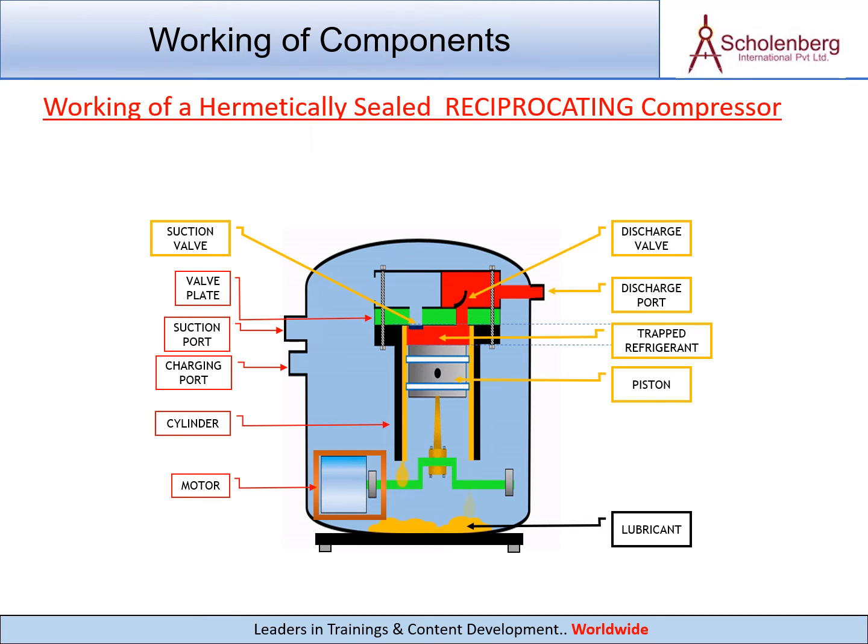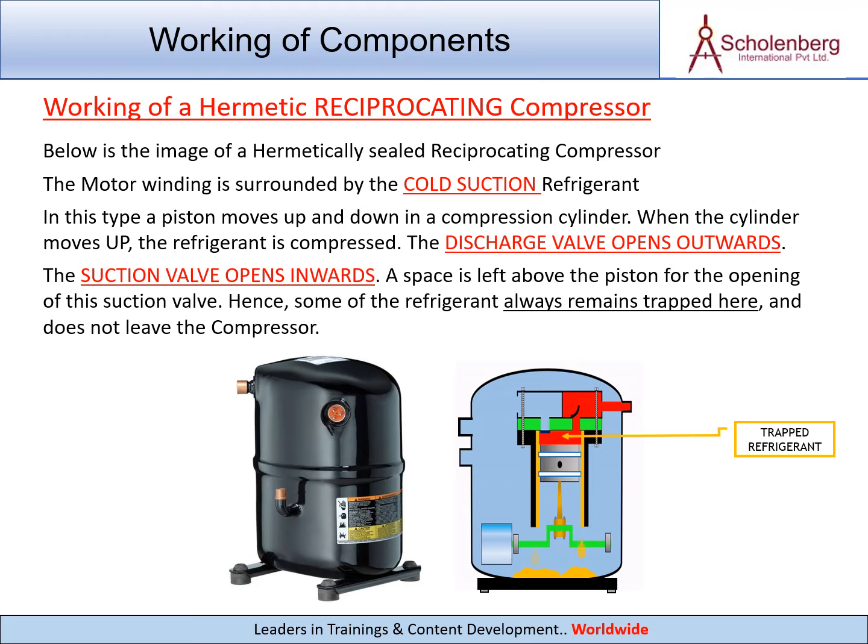Working of a hermetically sealed reciprocating compressor. Below is the image of a hermetically sealed reciprocating compressor. The motor winding is surrounded by the cold suction refrigerant. In this type a piston moves up and down in a compression cylinder. When the piston moves up, the refrigerant is compressed.